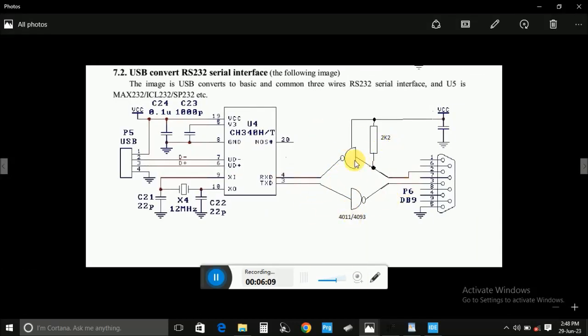Okay, you can use transistors to actually do the conversion, because the UART signals are a conversion of the original transmitted signals. So you need an inverter, an inverting circuit. So we are transmitting 5 volts and 0 volts actually, and that we should do for a programmer. So this is what I did with my programmer. Okay, and it's a simple circuit.